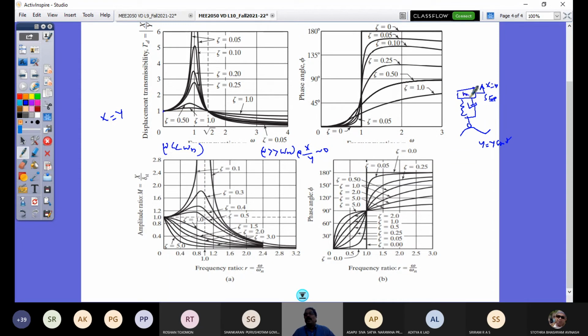The natural frequency of the sprung mass is omega n equals the square root of k equivalent by ms, which is some value. In hertz, it is 1 hertz. So how do you get it in hertz? 2 pi fs is equal to omega ns, so fs is equal to omega ns by 2 pi.